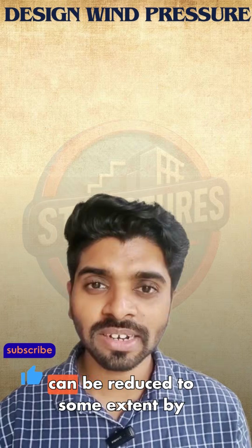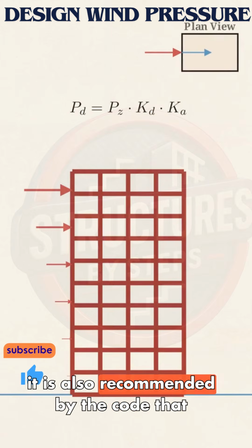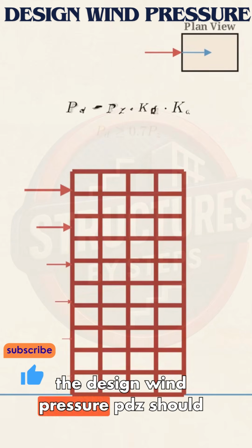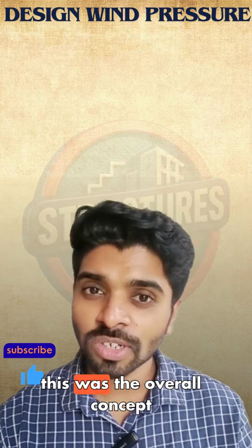So the design wind pressure can be reduced to some extent by using these three reduction factors. And it is also recommended by the code that the design wind pressure PDZ should not be less than 0.7 times PZ. So this was the overall concept.